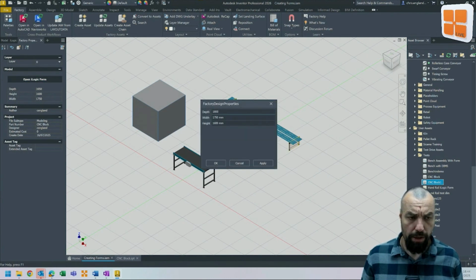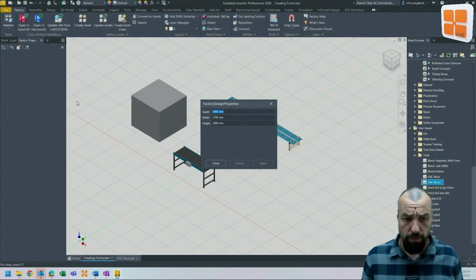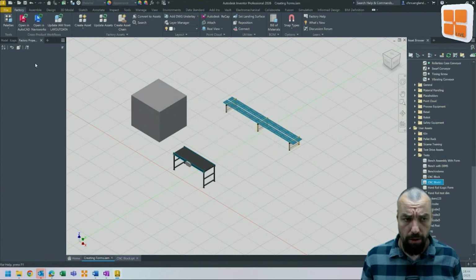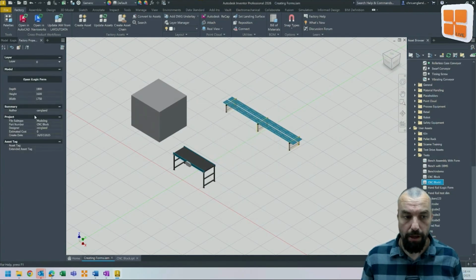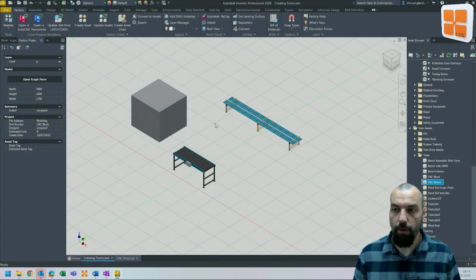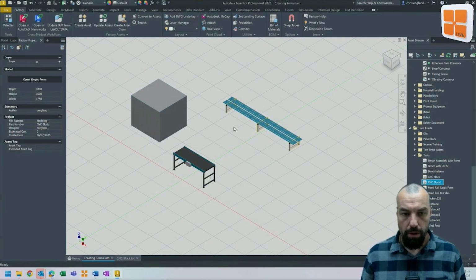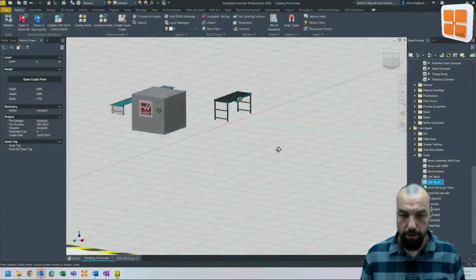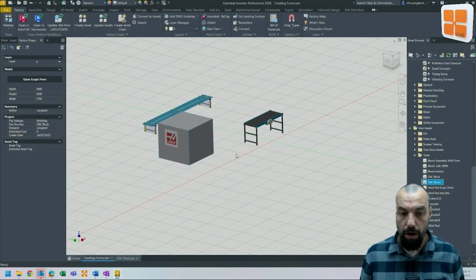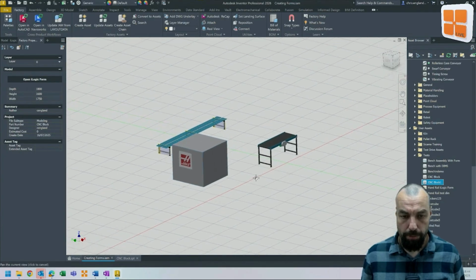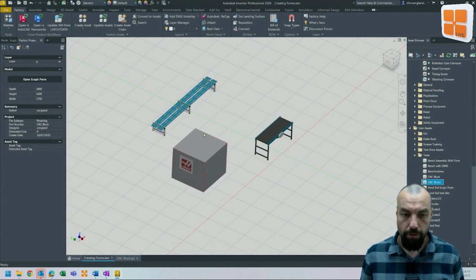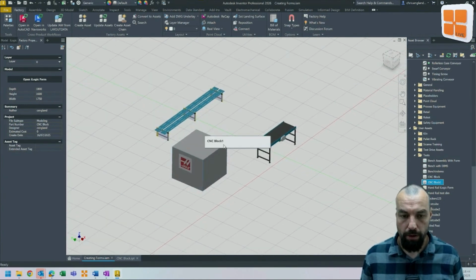And as a word of warning, if you are planning to use the forms to drive either iLogic or just parametric factory assets, bear in mind that the form will not work on the AutoCAD side. So if you're wanting to use this workflow, you would be sizing up your models or changing the parametrics of them on the Inventor side and not so much on the AutoCAD side, which I tend to prefer anyway, especially if it's a more complex assembly like this bench over here, as it just tends to be a bit quicker on the Inventor side.